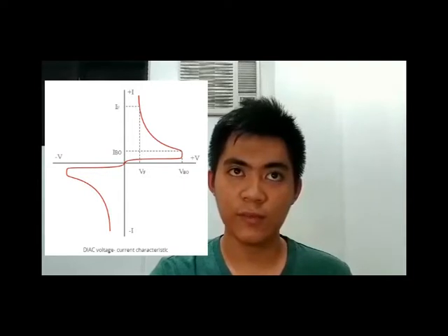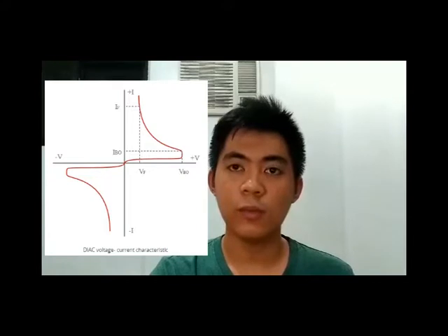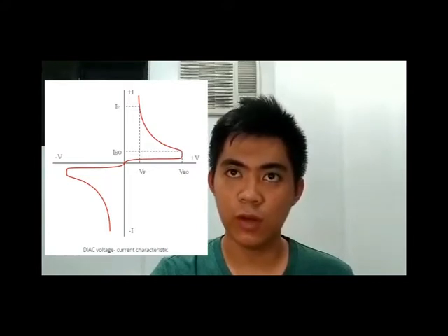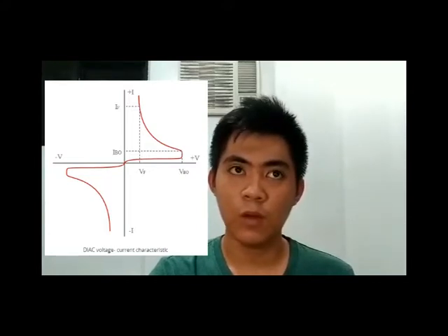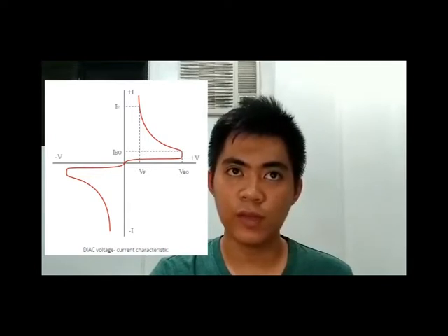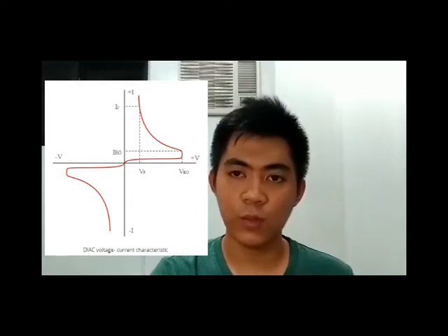Most Diacs have a breakdown voltage of around 30 volts, although exact specifications depend upon the particular type of device. Interestingly, their behavior is somewhat similar to a neon lamp, although they offer a far more precise switch-on voltage and thereby provide a far better degree of switching equalization.